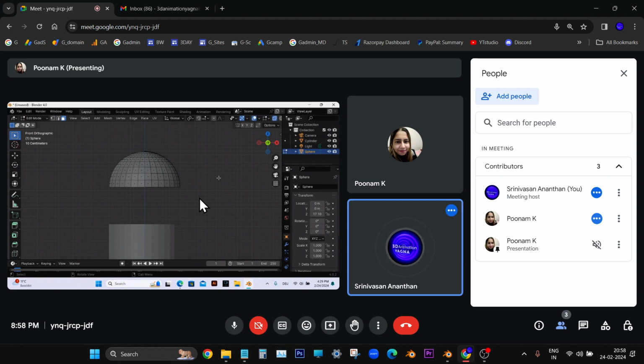Whatever is visible on the front side, only that will be selected. So we should be aware, whenever we are selecting any faces or vertices, whether X-ray mode is on or off. We should check, and then based on our requirement we should switch it on or off. Right.